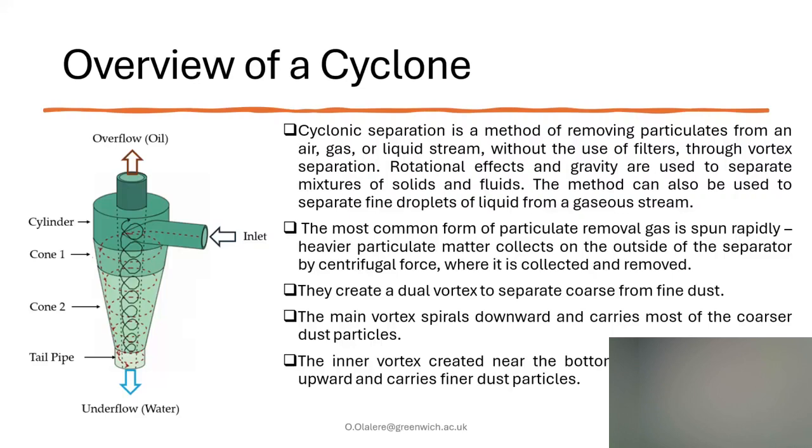Most times we use cyclonic separation before moving to filtration. The reason is that the majority of our particles will have been removed using cyclonic separation, and by the time we pass it through the filtration system, we have no need to do too much maintenance on the filter. That is why, when we have an integrated system, we can add cyclonic separation to it for optimal performance. So cyclonic separation removes particulate from air, gas or liquid stream without the use of filter. The most common form of